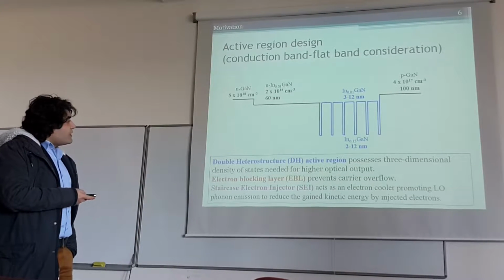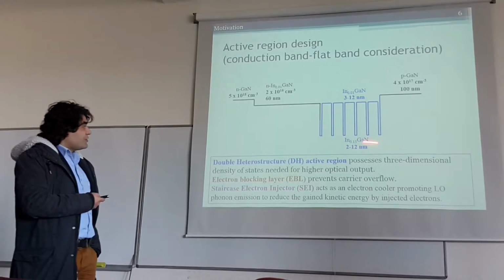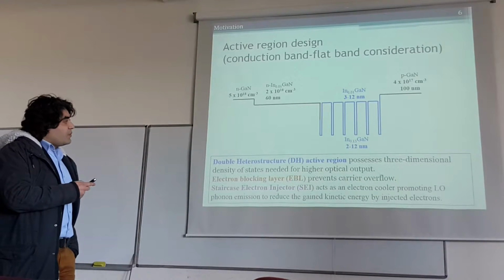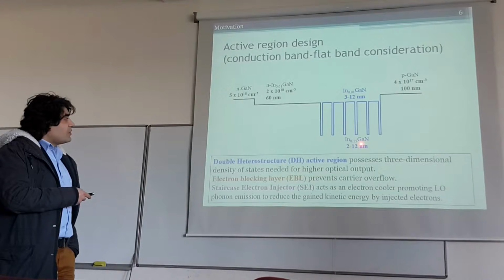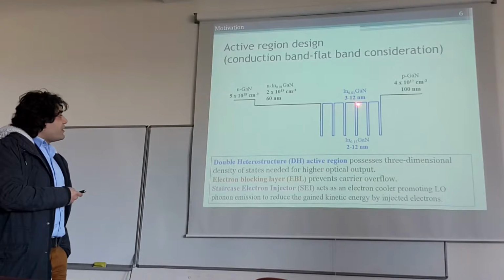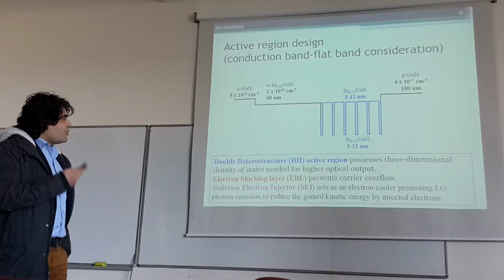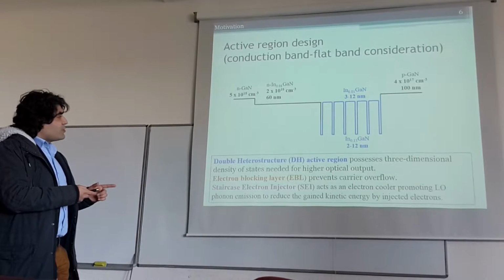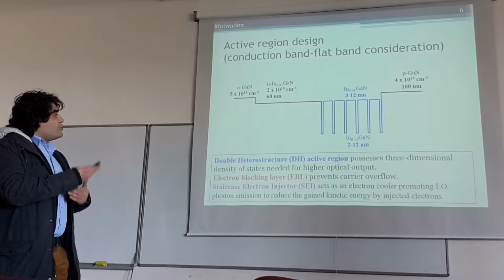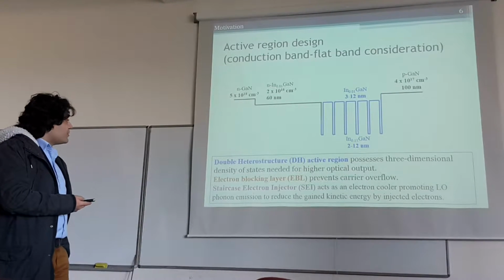As I told you, we had non-uniform carrier distribution in the active region. This is a 2 nanometer quantum well, 15% indium gallium nitride, right? Emitting around 430 nanometer. And these are the barriers. With this 1%, it may change. And we thought we may increase the thickness of the active region to change the carrier density in the active region to decrease the efficiency loss problem.